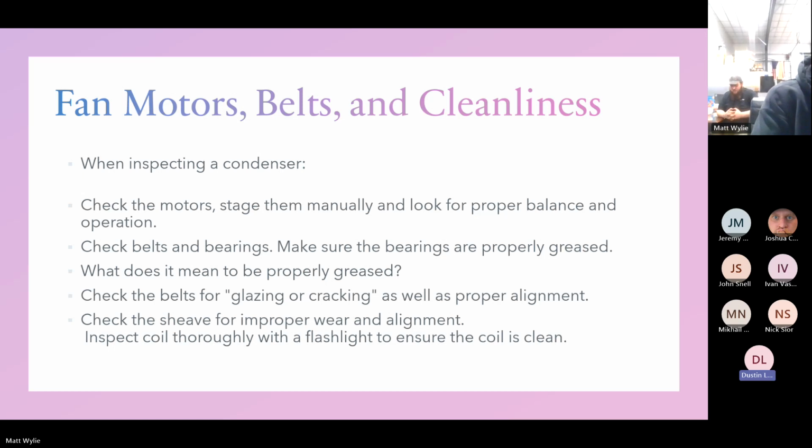And then, like Derek said, when it reaches a certain temperature, you're just slowly metering a small amount of refrigerant in to keep the head down. I think it's usually only on the scroll units, right? Just because they run so hot, you won't see it on some of the older K-body style ones, but it just keeps the heads of the compressors cool. There's an internal temperature rating, and if it starts reaching that, it feeds a little bit of liquid off your liquid line in there to cool it back off. But really, you shouldn't rely heavily on that. You need to get your superheat right to have cool gas cooling your compressor, right? Yep.